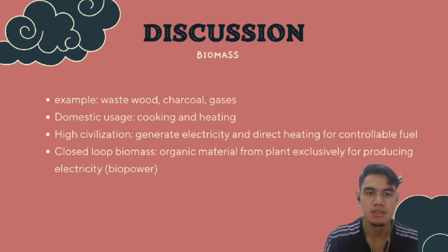Wood biomass contains sulfur and nitrogen, which yield air pollutants, sulfur dioxide and nitrogen dioxide, though in much lower quantities than coal combustion. Biomass fuel cycles are often not greenhouse neutral because of the substantial production of products of incomplete combustion. In Thailand, biomass power plants that produce less than 10 million watts using rice husk combustion systems have the potential to burden nearby villages with environmental damage such as air and water pollution due to black ash from smoke and dust, and also cause health problems for people.